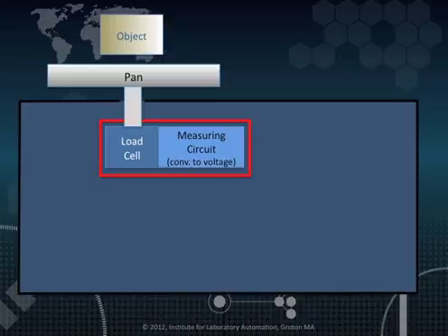For example, if we wanted to measure the movement of a pendulum swinging back and forth on a shaft to an electrical signal, we would attach a variable resistor to that shaft that supports the pendulum and use a circuit that converts resistance to voltage to get that electrical signal. As the shaft rotates, the value of the resistance changes, which can be converted into a changing voltage.